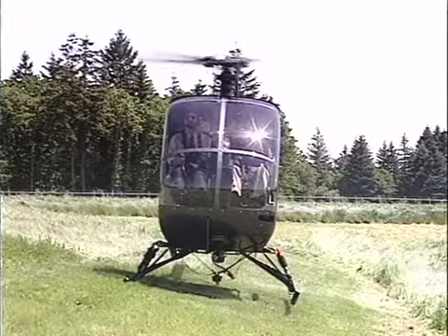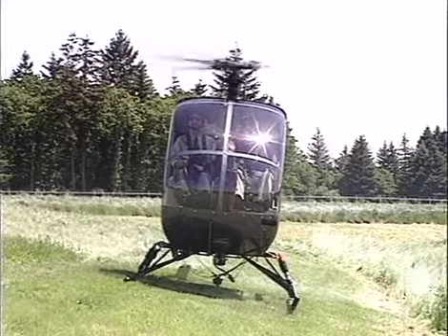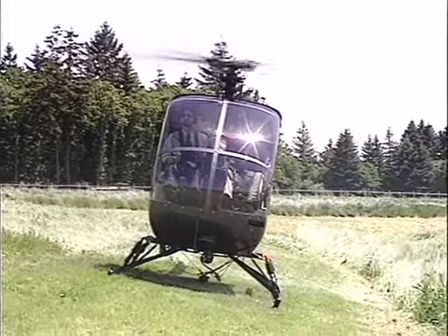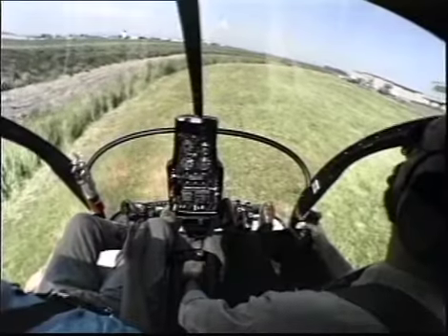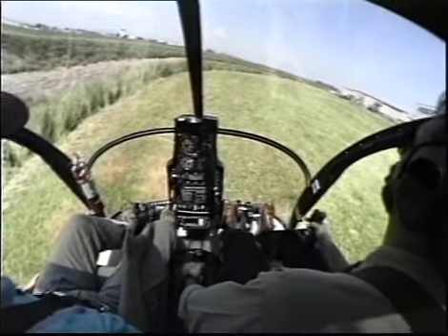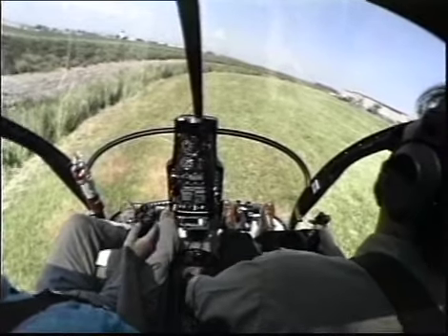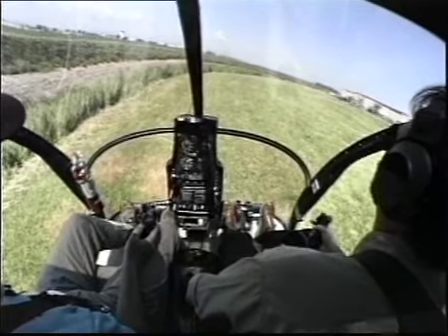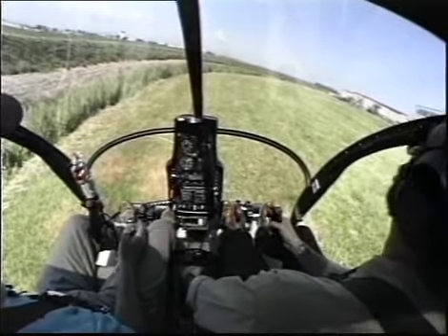This helps you maintain a fixed position without any forward, aft, or downslope movement. Continue to apply downward pressure on the collective pitch control to lower the downslope skid to the ground. Use the anti-torque pedals to maintain a constant heading throughout the entire maneuver. Maintain normal RPM until the full weight of the aircraft is on the skids, in case you need to make an immediate takeoff due to unstable ground or a slope that's too steep.